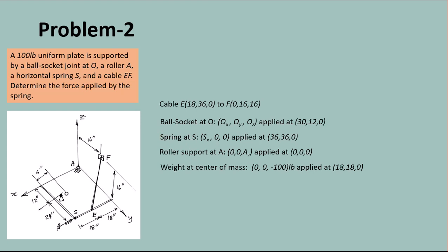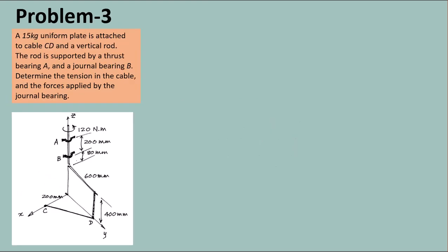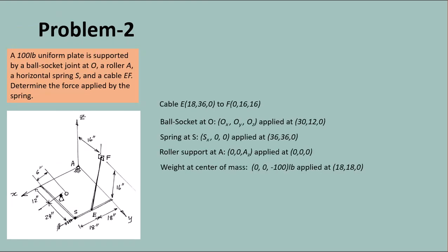Spring at S, we can model the spring as a cable, but we are going to model the spring as a pin, just because the spring is aligned with the x-axis. It applies only an x force, and it's located at 36 along x and 36 along y.